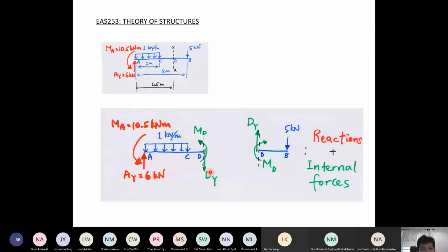But it's not necessarily 0 all the time. For a beam, normally there is 0 axial force, the internal force, unless you have a load which is acting in the x direction, along the axis of the member. Then in certain parts, you get axial force. So the green color here, these are internal forces. These are the shear force and bending moment. These are the forces which are unknown that we need to do analysis to determine.